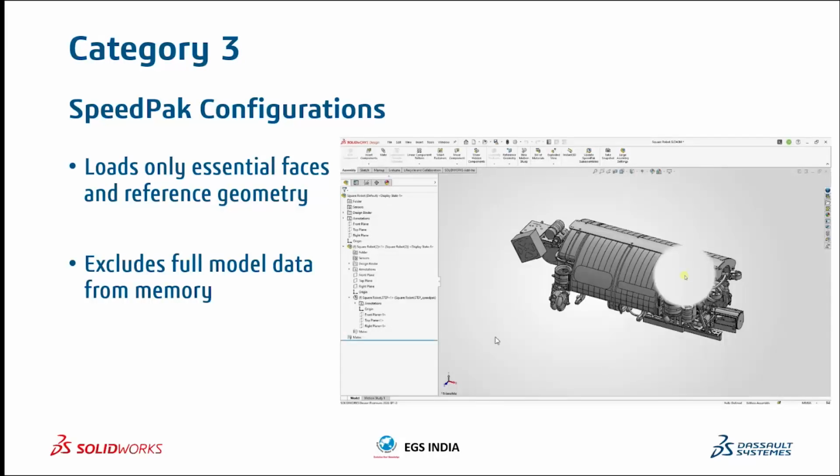In this example, you can see that there is a ghost circle seen when the cursor is over the parts. This is because the entire subassembly has been converted into a speed pack. When using the speed pack configuration, the structure system or other components, this data is similar to an image. So basically, just a graphical representation and not the model data entirely.